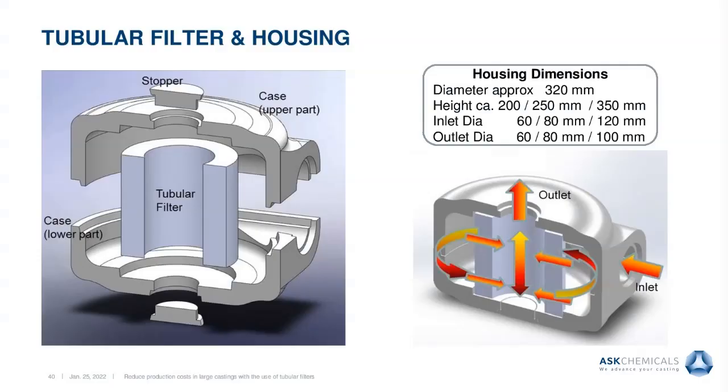The use and the installation of the tubular filters within the mold are different, but no more difficult than the use of any standard plate filters. In fact, the installation of this filter is simplified because tubular filters are designed for easy installation within the mold near the mold cavity. You can also place them directly near the next ingate, or you can use a suitable filter print.